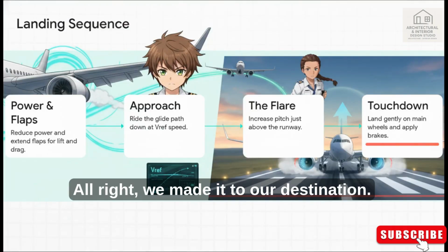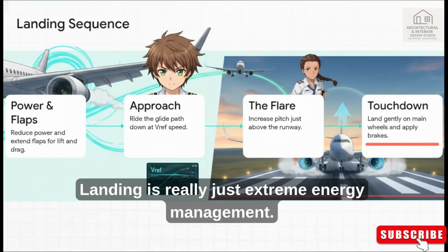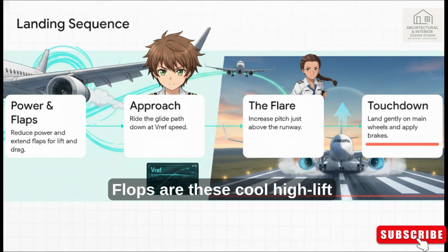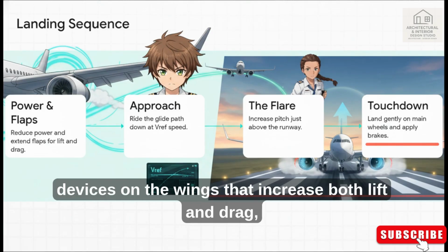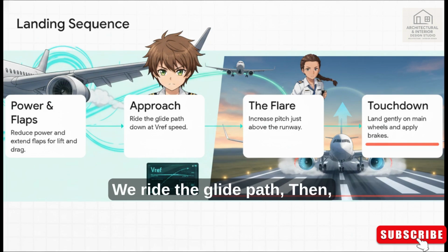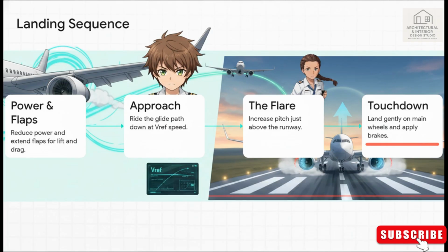All right, we made it to our destination. Landing is really just extreme energy management. First up, we reduce power and extend the flaps. Flaps are these cool high-lift devices on the wings that increase both lift and drag, letting us fly a lot slower without stalling. We ride the glide path down at a specific calculated approach speed, which we call VREF.